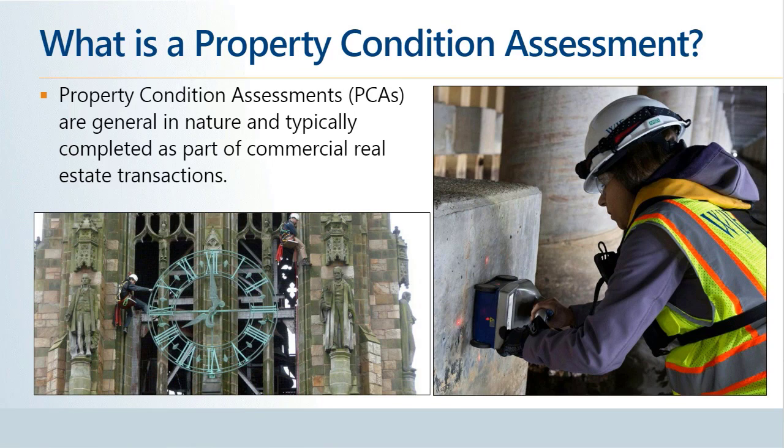The complexity, invasiveness, and time required to complete assessments varies, primarily based on comprehensiveness. Assessments can be very limited and brief, with accordingly limited findings, or they can be much more comprehensive, including detailed reviews, close-range surveys, inspection openings, non-destructive testing, and other means of establishing a highly detailed understanding of the condition of a structure. All of these assessments have their place.